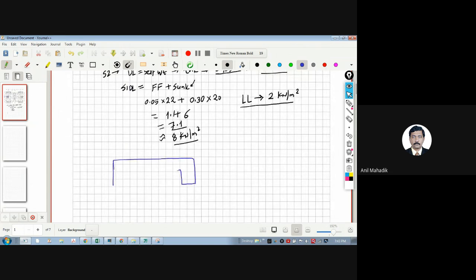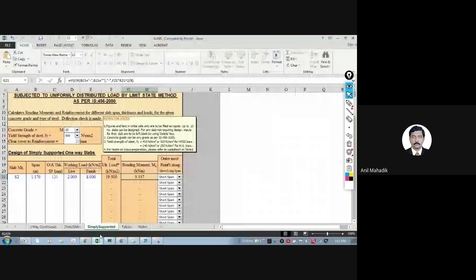It will look like, let's say this is your beam and this is your slab, and this is your 1.17 meters, 1170 mm. So your main steel is this horizontal blue color, and you will have the distribution bars above that. So the dots are above this. And why do we do this? Because we get more effective depth. So in similar fashion, it is asking where you want to put the reinforcement. So we want main steel along the short span.